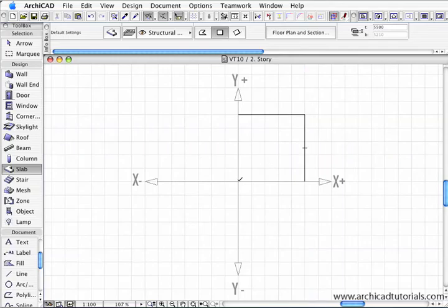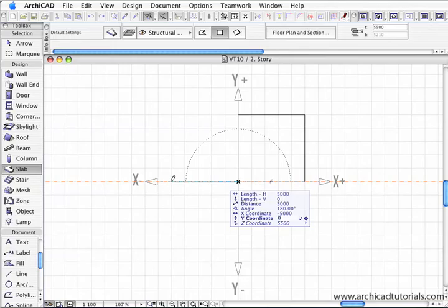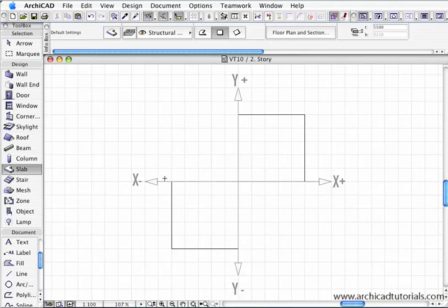If I wanted to go in a negative direction, in other words, make the slab go the other way, so if I left mouse click here and move my cursor in this direction here, so it already knows it's going in the negative direction, and I type 5 meters, then y 5 meters minus enter. Now it assumed that because I took my cursor to the left, it assumed the negative direction, and then I typed the negative to go down south of the page, and so we've got the positive and the negative slabs over here.